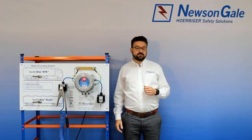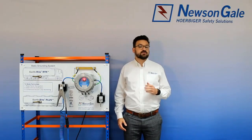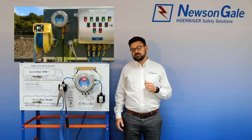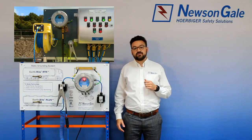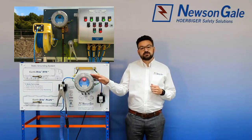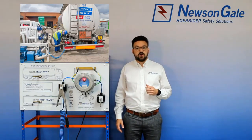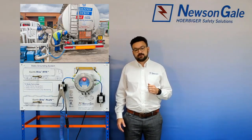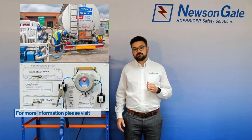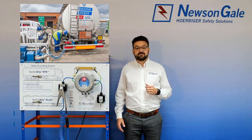The RTR system performs 2 key checks that enables 3 critical functions. The first check is capacitance and earth verification function. The system outputs a signal and looks to detect a connection to isolated metal plant equipment with a capacitance footprint typical to that of a road tanker. The same check also measures the soil resistivity to less than 1000 ohms resistance based on the NFPA 77 benchmark value.